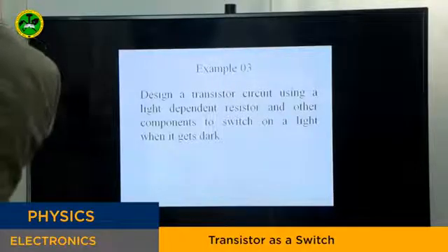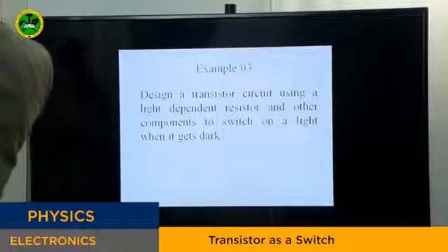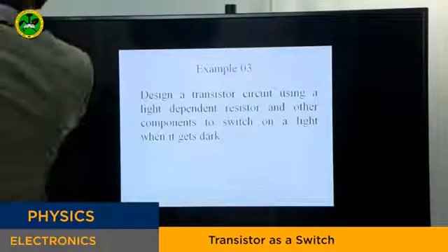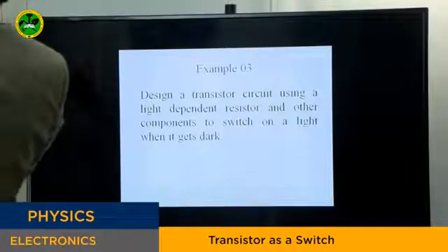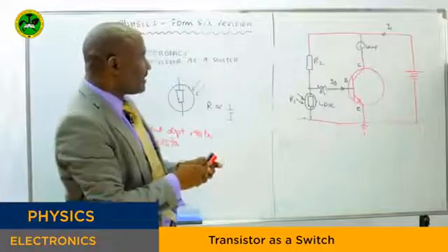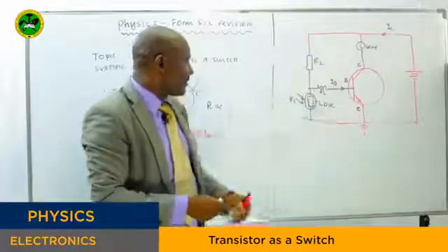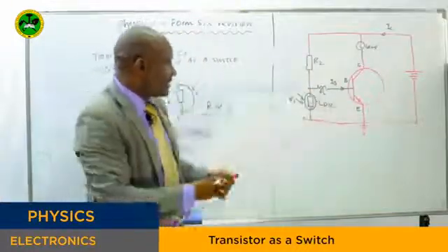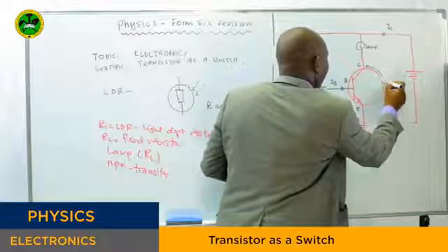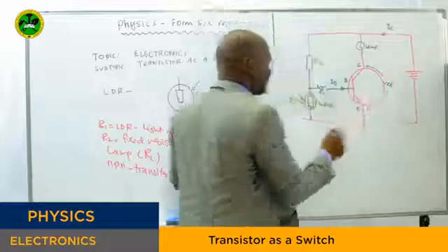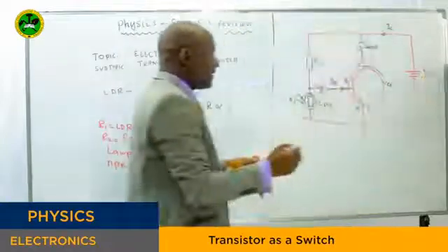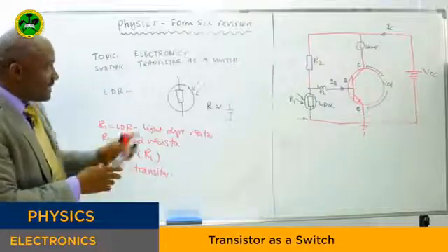This is our R1, this is our R2. So the supply voltage, some will be coming here, and they can produce the base current. The one which determines the base current is the voltage across here. So now let's see, this is what we call VBE and VCE here, and there's where we have the VBE. This is our supply voltage, which is given. Now, the circuit is drawn.